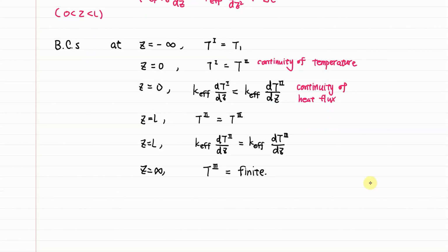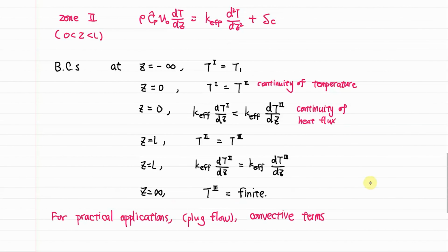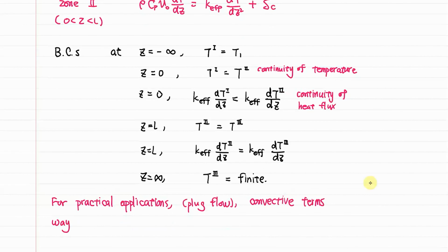So for practical applications, in plug flow reactors specifically, the convective terms are way more important than the conductive terms. So we will drop the conductive terms.